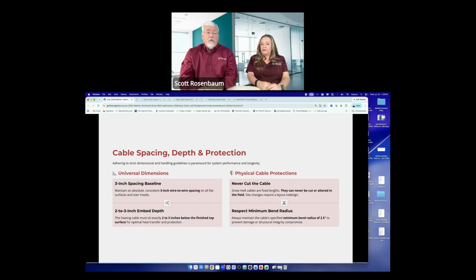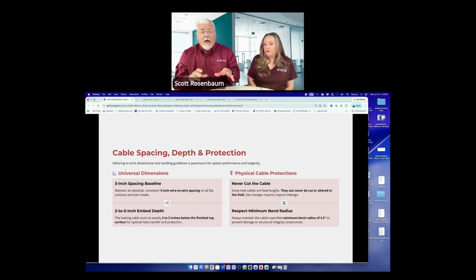Right. Now, what I talk to people that get the spacing wrong is they will say, I know you designed it for 3, but I installed it on 4 because I forgot. I did 4-inch spacing. And now all my pavers are in, and I've taken all the excess cable and put it in a spool sitting next to it. I've talked to people 24 times that have done that. You can't do that. You have to use that cable because there's nowhere else.